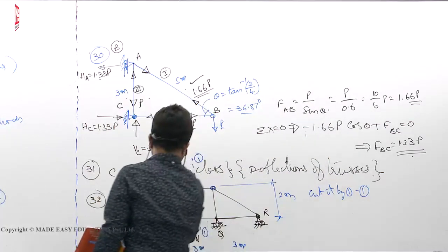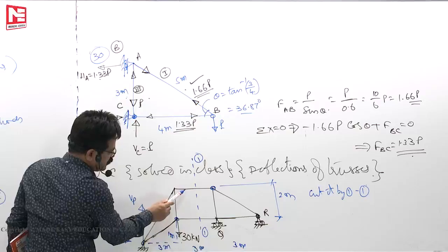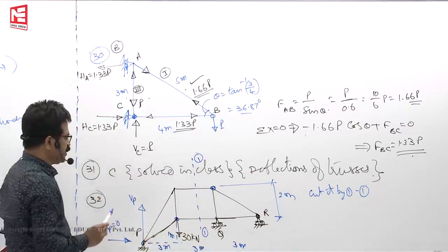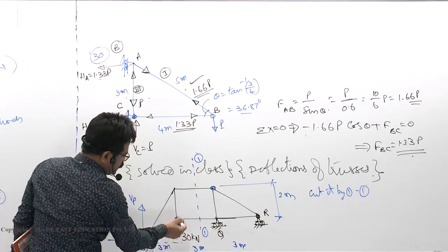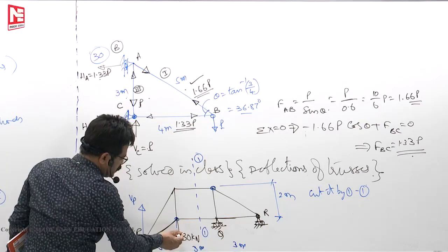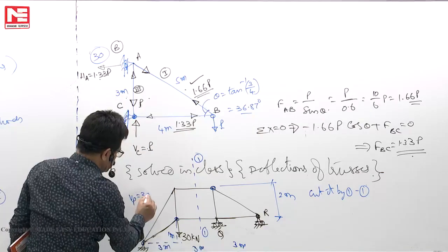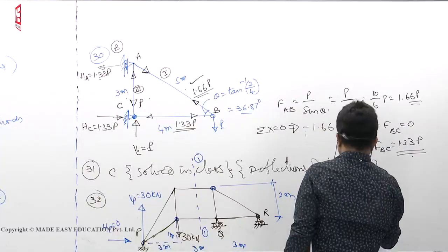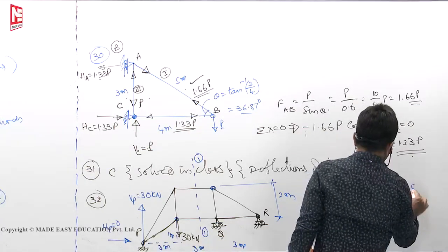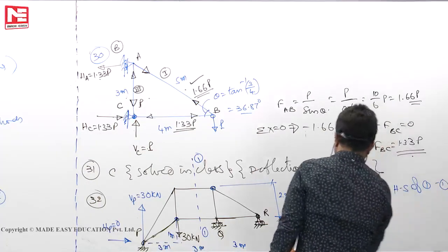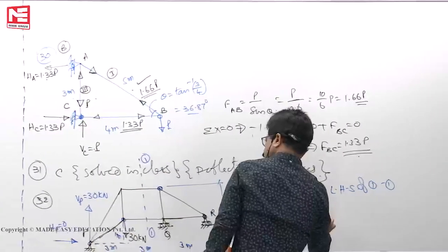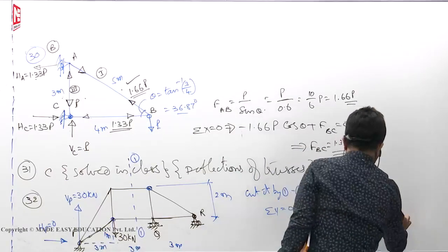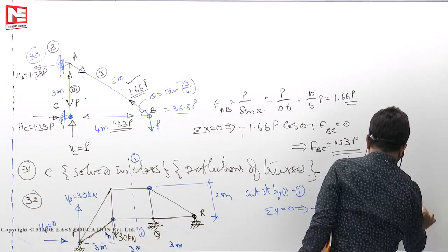Okay. Look left side. When you look left side, this force and this force are horizontal. That means they will not give any vertical component. So, left side if you see 30 down, to balance 30 down, here it should be 30 up. Then take LHS of 1, 1. You can apply sigma y 0: plus Vp minus 30 is equal to 0. So, Vp has to be 30 kilonewton.